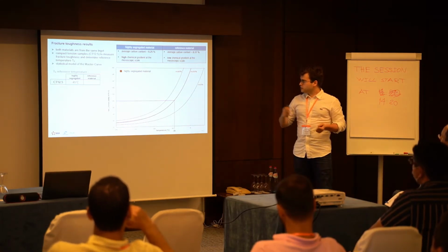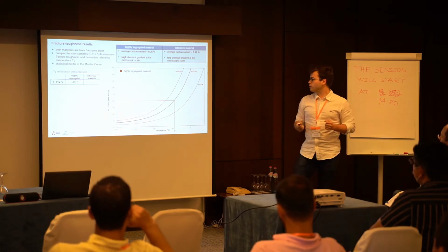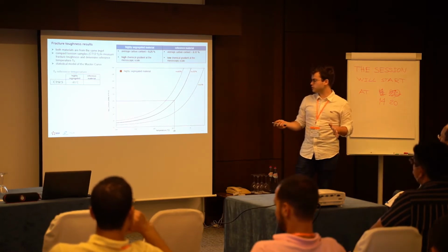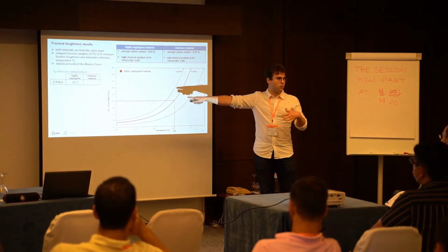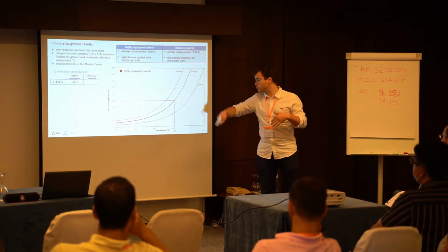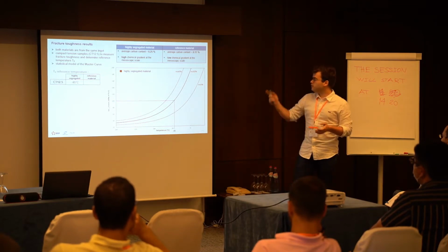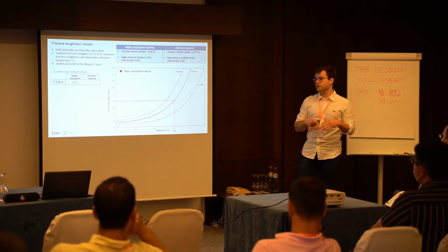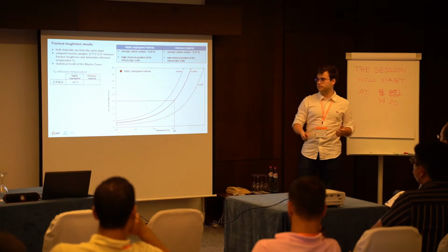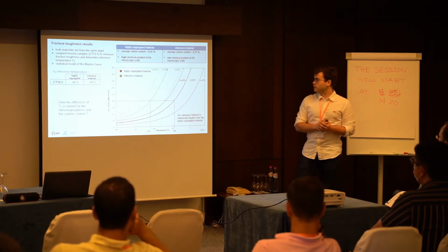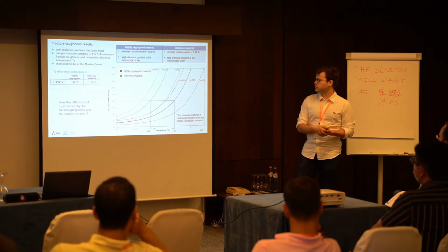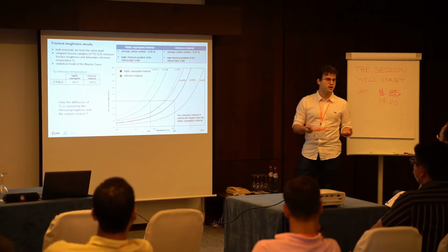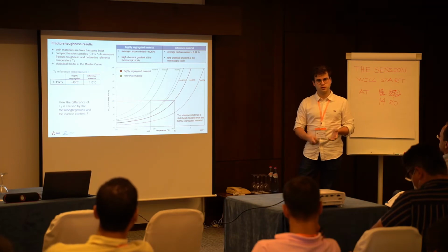And the T0 reference temperature is the temperature where the median KJC is equal to 100 MPa square root of meter. For this material, the reference temperature is -45 degrees. For the reference material, more homogeneous, the reference temperature is much lower, minus 110 degrees.